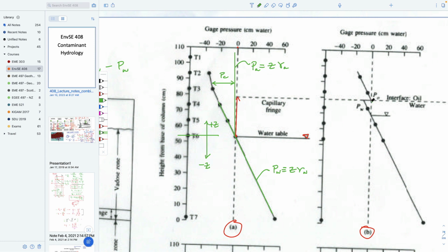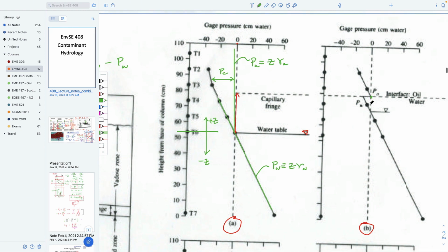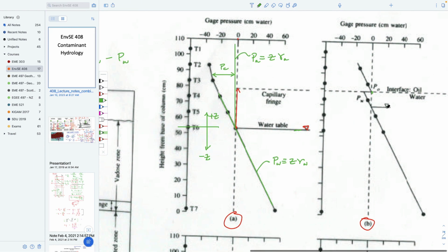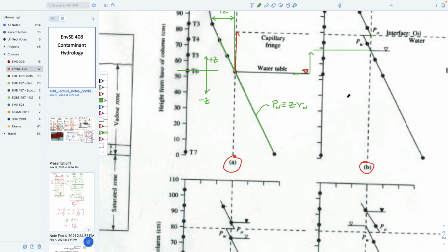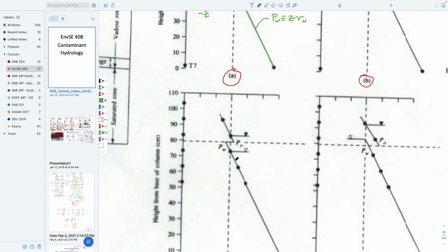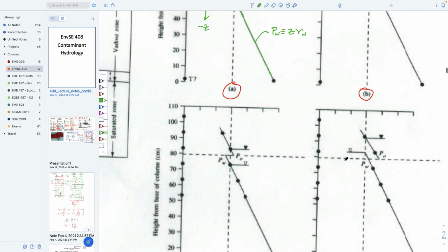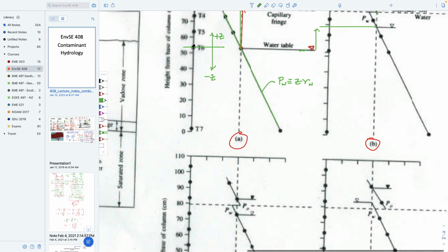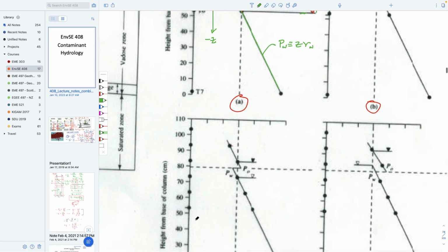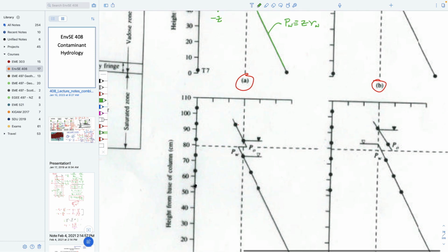And as you get this nose coming down, further compressing it, the water table, instead of being here, has risen to this point because it's being compressed by this gasoline on top of it. As it keeps on moving down, the pressures change. The water table actually rises from its initial point, which was equal to 55 centimeters, which would have been down here and down here.